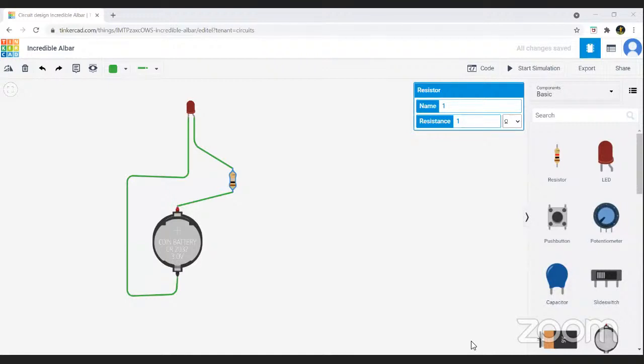Right now we are only using these components. We are not using any other. Yes, I can repeat, for those who want me to repeat. For the resistance value, you have to change the unit from kilo ohm to ohm. By default, it will always take the value, so if you see here, the value of the resistance will be 1 by default. Okay.